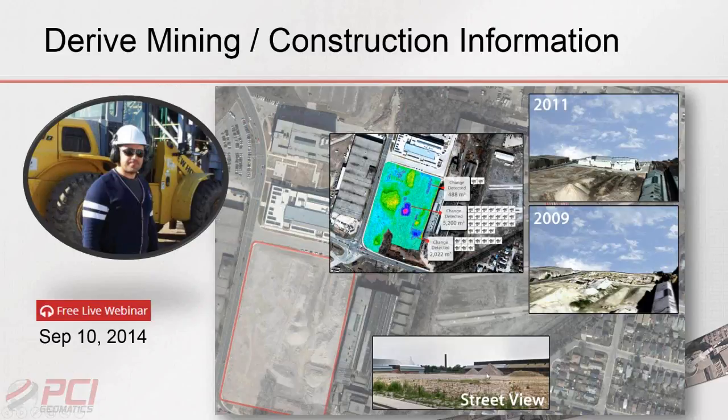In this case, these stockpiles. You can see the stockpiles here in the roadside imagery that was taken next to this building. And we're able to identify those stockpiles and measure the volumetric information that is contained in them. So, although imagery sometimes is just used as a backdrop, through some simple processing in our software, we can extract elevation models, which Sean will be explaining and showing to you, and also using ArcGIS, we can calculate volumetric information and quantify the sizes of the stockpiles, which can really be used for operational decision making.